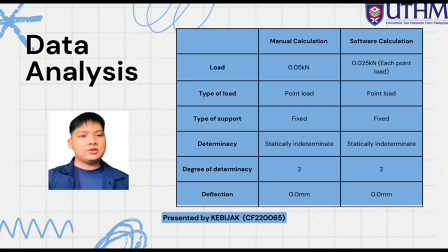Point loads are used because in the actual design, the beams are not level with the peak of the column and load transfers directly to the tower column. In testing, the tower held 11.2 kg for 30 seconds and fell at 15.2 kg. It was designed to withstand a maximum of 10 kg, so the tower structure fell.